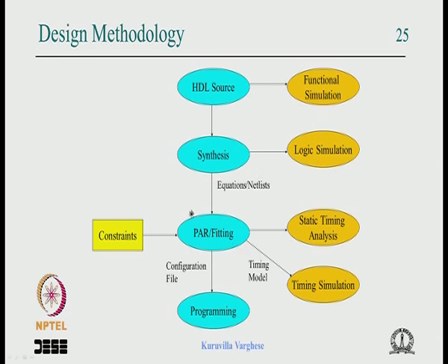But normally the place and route is done by the vendor, because the vendor knows the FPGA internal details, which are very much required for doing that properly. And many times it's not wise to give out these details, because people can make out what is really inside. Though we have the data sheet, not all the details are exposed, to keep the intellectual property.